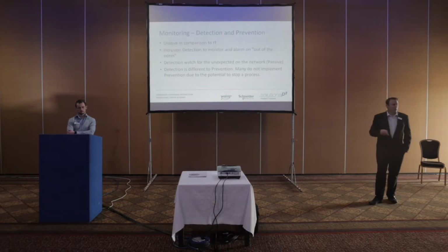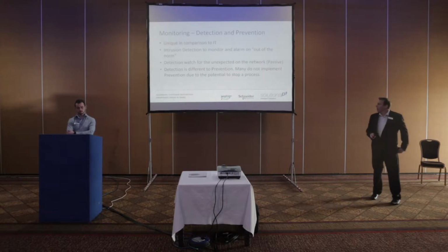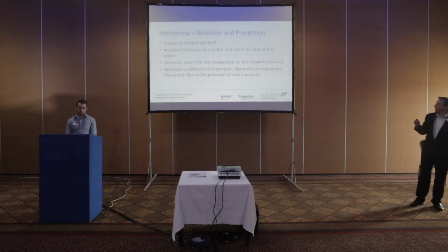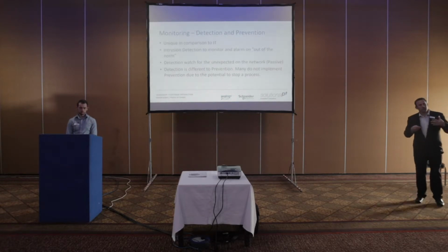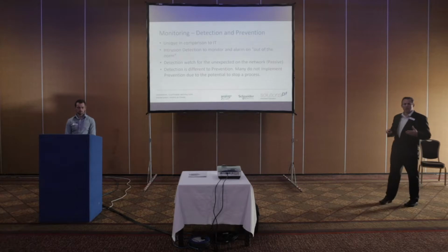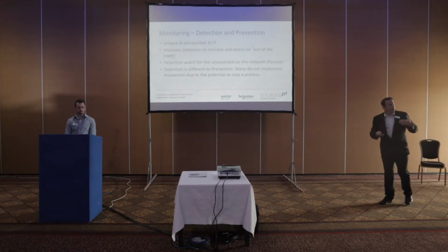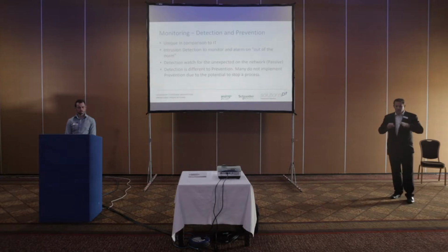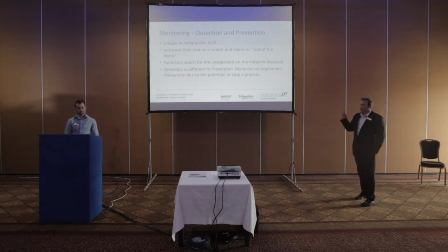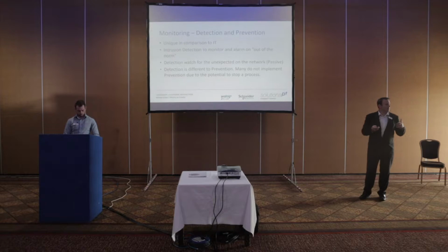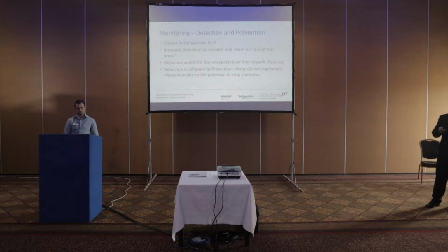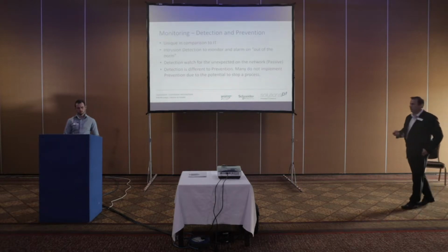If we then look at monitoring, what kind of monitoring systems can we get on our network? Obviously, there's the two, intrusion detection and intrusion prevention systems. Control systems are very unique compared to the IT layer. The amount of traffic is by far more, but it's actually more deterministic. You actually understand what kind of traffic is going to be running on your SCADA and PLC level. Also, intrusion detection looks at monitoring for out of the norm limits. So it basically monitors and then flags up any sort of traffic that it doesn't understand or doesn't actually fit.